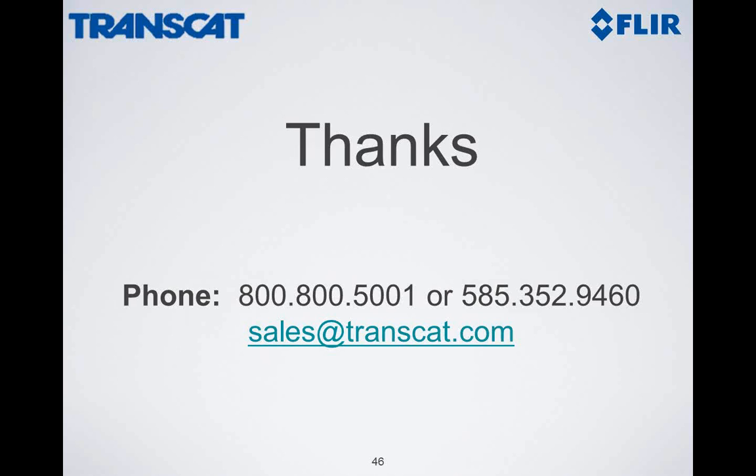What you can do is put an area max tool on your image and then slightly adjust the focus and watch the temperature in the max tool. As it goes up, you're getting closer to true focus. Once it peaks, and then goes over the peak and the temperature starts going down, you back the focus up once, to the last setting, and that's where true focus is.